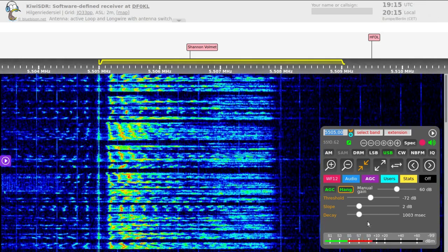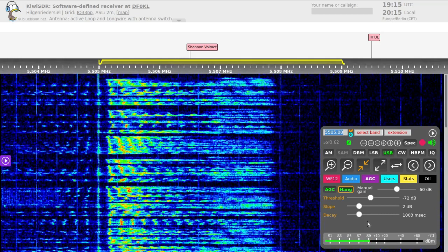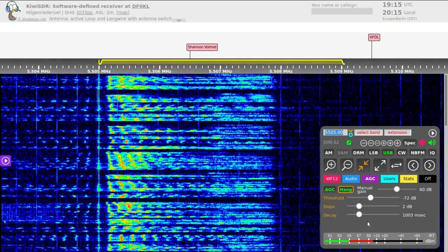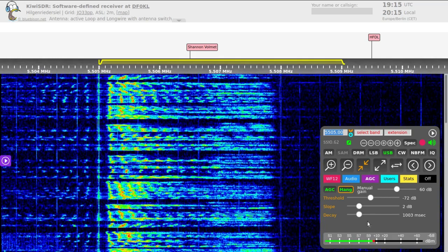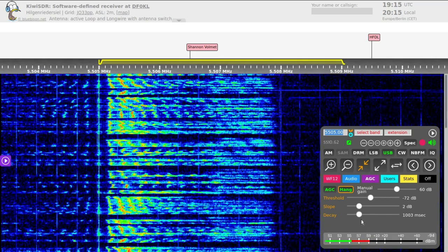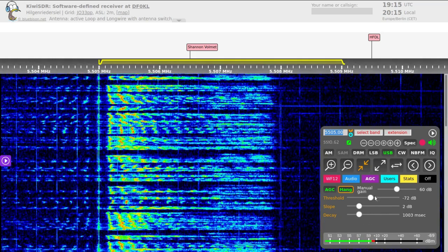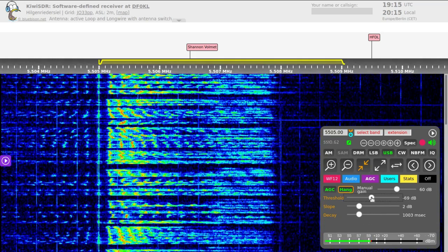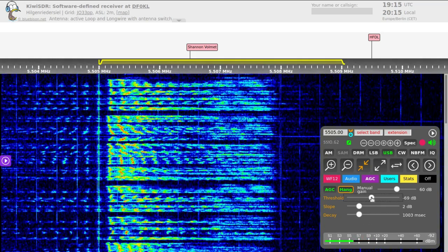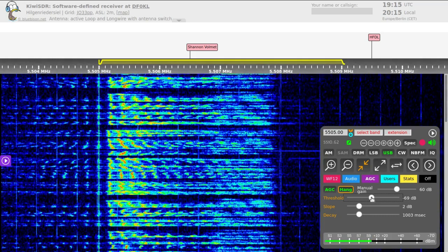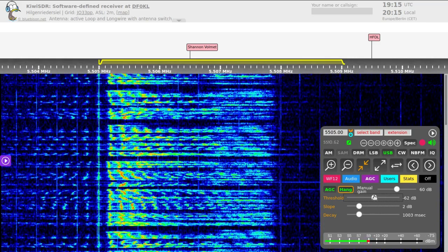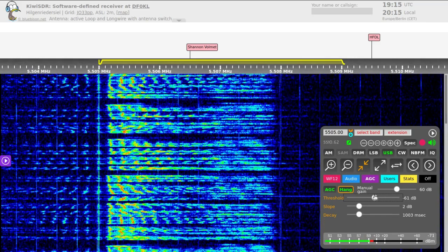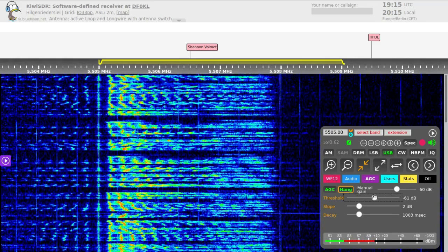And these will be more noticeable if the signal takes a very strong fade up in strength, or if it drops down in strength because of threshold setting. You'll be protected from excessive bursts of noise. And you can make fine adjustments, a few dB this way, a few dB that way, until the level of background noise is suitable for your recording.